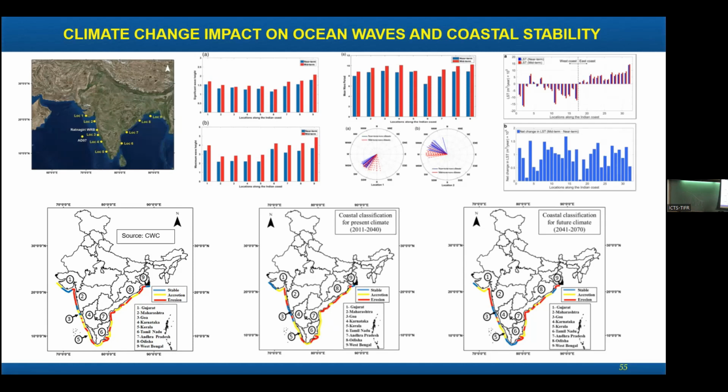Now, in most of the cases, if you want to go for design of anything, you cannot design for different wave heights. You need a single value. You want to design this building and you want to find out what is the force that is going to come. You tell me the maximum, that's fine, but you cannot tell 100 values. So similarly, in this case, if I have to tell a single value, what should I say? Maximum. If I say the maximum, then I might be overestimating. So we have something called significant wave height. We define it as HS, significant wave height.